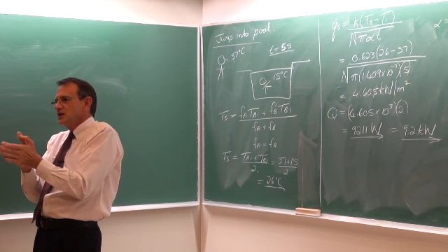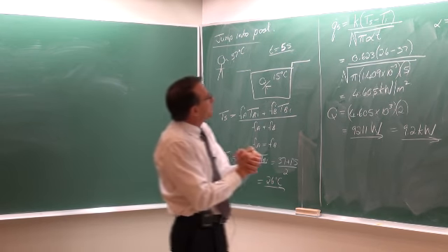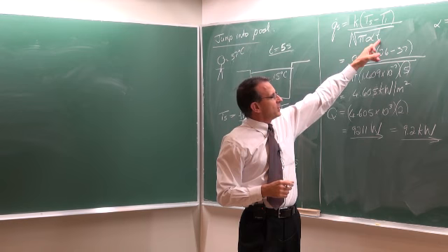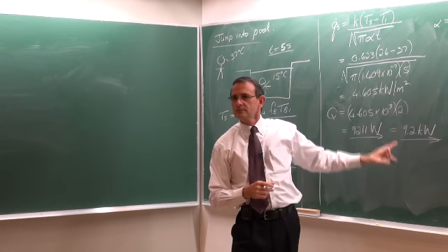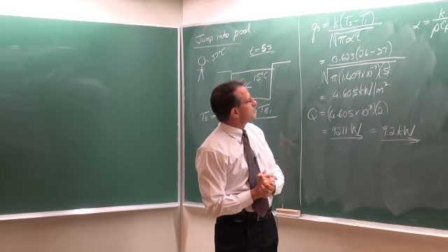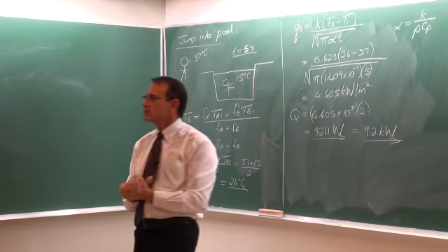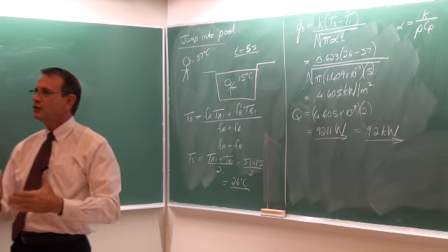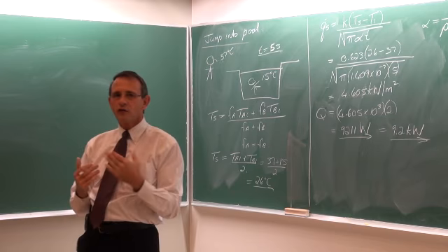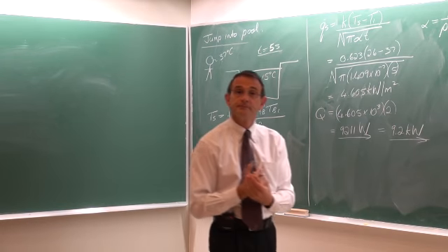But after T equals 0, then we can. So if T was equal to 0.1 seconds, the heat flux most probably would go into the megawatts per square meter. An enormous amount of heat which is being transferred from you to the water.